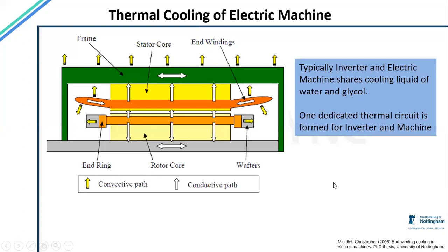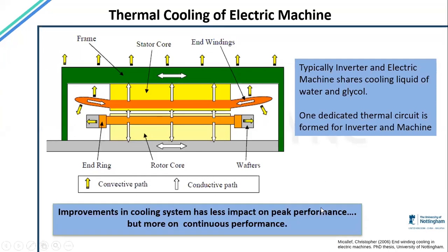The end winding cooling is very important because they are all in air, so we have very high thermal resistance in this area. So how to cool these? Whether we should have some dripping over here, or some shaft cooling, as we call it. These are all different studies that we have to do: thermal resistances, conductivities, and those governing equations.